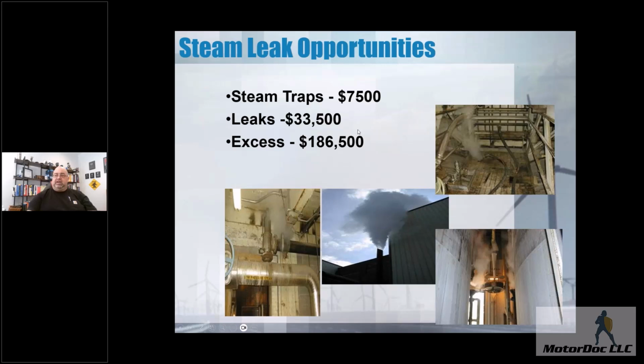So when we were done, steam traps, 10% of steam traps fail per year. And in another case, we came up with a way to reduce the impact in automotive. It's applicable elsewhere. There are steam traps that are live swappable, meaning you shut some valves, you pull out the old one, put in a new one. That reduces it and allows you to use things like your ultrasonic, infrared, and other tools to identify good and bad steam traps. That's an impact.